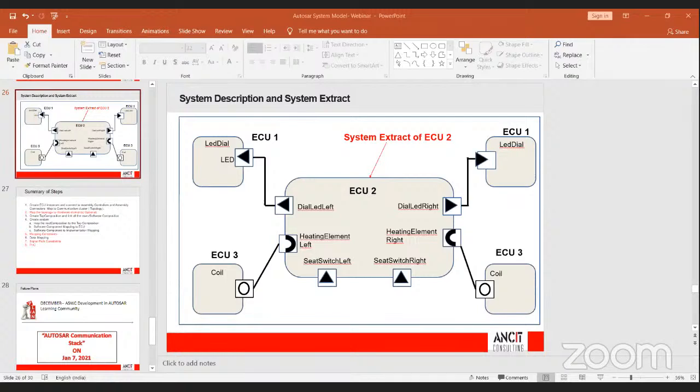Why do we need two ECU instances here? Then you will configure the ECU for only one instance, right? Yes, you are right. You don't need two instances, but when I build the application software component, I will support multiple instantiations. So I can copy one instance in one memory location and another instance in another memory location. Both those software instances will be doing the same work, but supporting left side and right side, one for the passenger and the other for the driver.